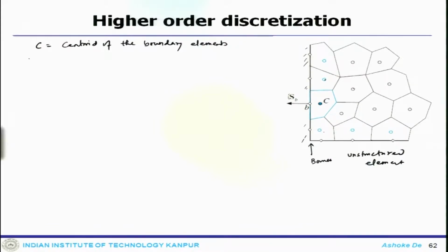So, the discretization of this particular cell would now become, for any dimensional system, in a generic system, the sum over faces of J_C dot S_F equals to 0.